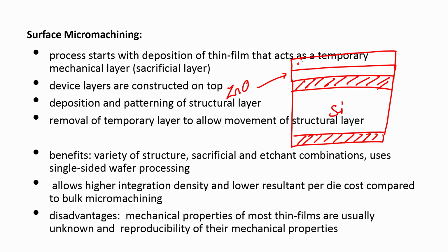Let us say this one is my photoresist, spin coating photoresist. The next step is soft bake, 90° for 1 minute on a hot plate. Next, I load a mask, a bright field mask like this.